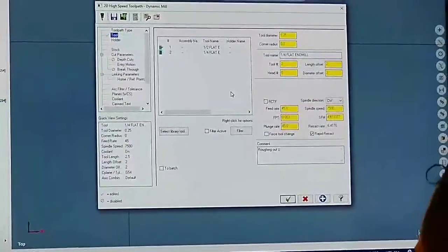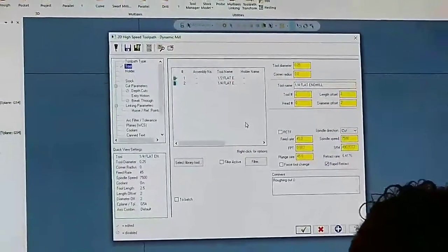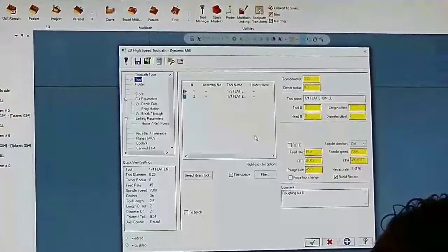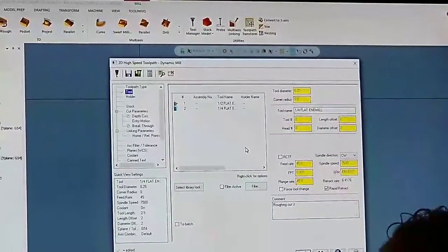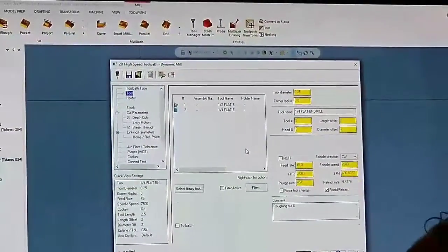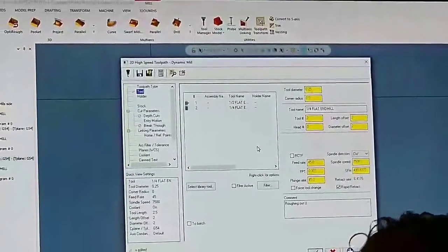We're going to approach the material differently than you've seen done before, so the tools react completely different. In a normal tool, if you came in there at 7,000 RPM and all that feed, yeah, it's going to want to break that tool off because it's too fast for it. When we go to a finish, we might adapt things a little bit, but right now we're still roughing. It'll knock that material out of there without an issue. We could honestly probably go twice as fast, and it'll still do it.